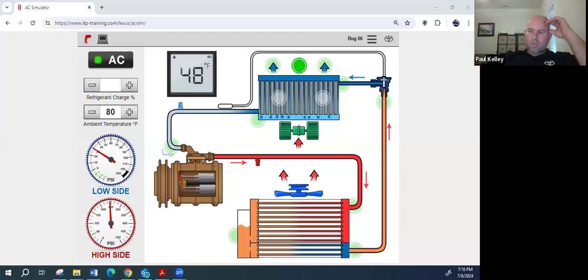And she said she's had to try to defend lemon law buyback cases when all the technician wrote were 3 letters. NPF. So if we rolled out and you felt this and it was like, oh, the AC's cold, NPF, no problem found. Now that wouldn't be the case on this because we know this customer did DIY repairs, but just consider the lesson there. NPF, what could you do better to demonstrate that you actually tried to duplicate the concern or you tried to verify the customer's problem? What would you do on this car?